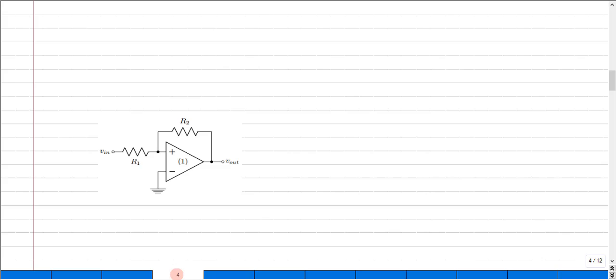Let me emphasize the word feedback amplifier here. Let me consider a simple op-amp. So this is a negative sign, which has been wrongly marked. The op-amp that I have here is basically built using a single-ended op-amp circuit, right? And what we have done is, we have used this R1 and R2 to create a negative feedback loop around this particular network. Now, can this feedback be called a common mode feedback? The question. Its obvious answer would be no. I cannot call this a kind of common mode feedback.